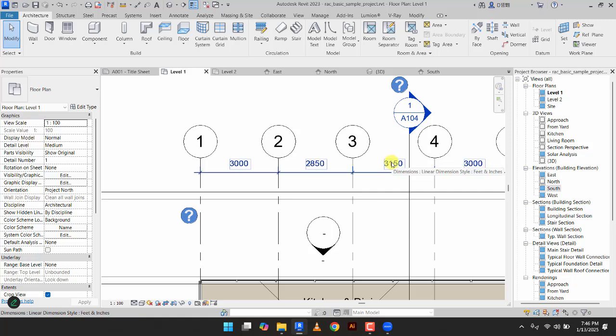So I'm going to change my project unit to what do I change it to? Feet. Right. To go to where you change your project unit, you find it under the manage tab. So on the tabs you see manage, right? I'll click on manage. Watch me. Let me do it. Will you watch me do it first? I beg you. I'll click on manage. Then under the manage tab, mine doesn't have a shortcut. The shortcut for project unit is UN.